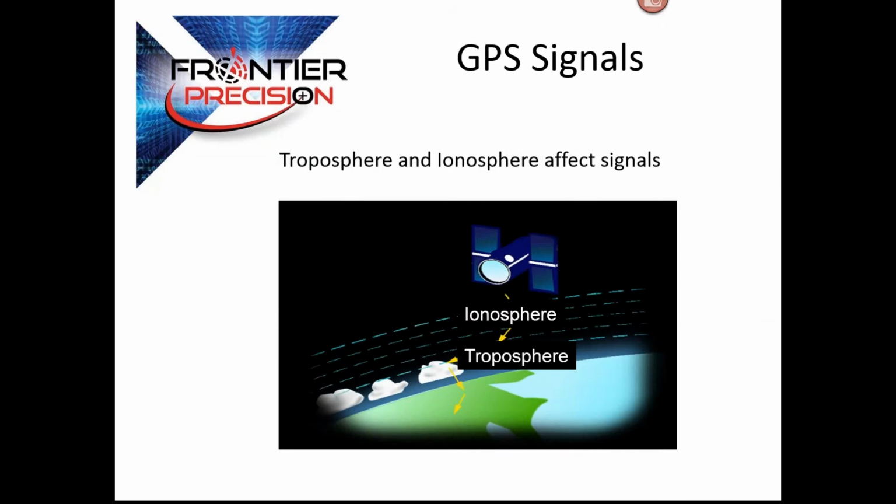And lastly, one of the weaknesses of single base or single reference station setups: the RTK system requires reception of satellite signals that must travel through the ionosphere, which contains charged particles, and then through our atmosphere, which is loaded with water vapor.